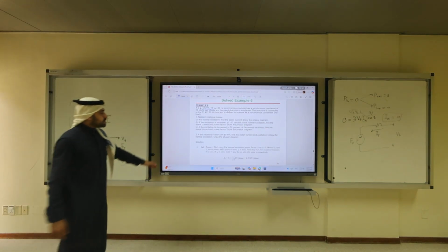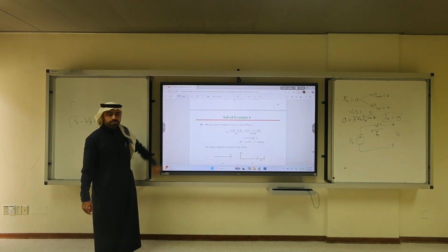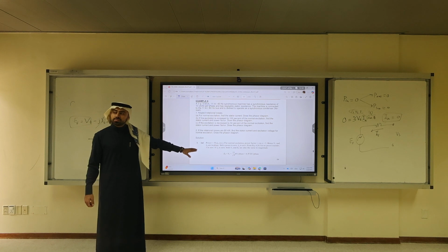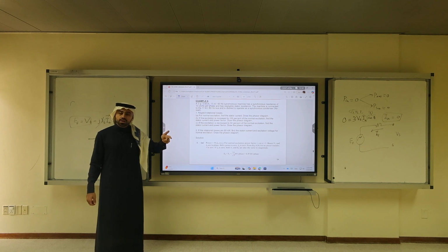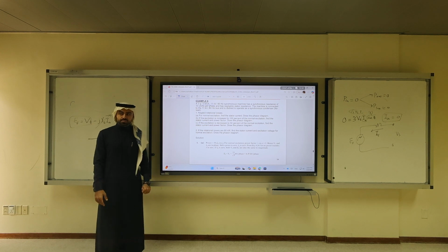Do you have any other questions? Next lecture we'll continue with part B, okay? Any question about part A? Why is IA 0? Because this motor is connected at no load and we ignore the losses, so it's like spending no energy. It's like an open circuit. Okay?